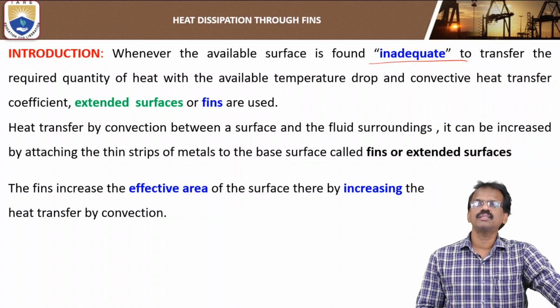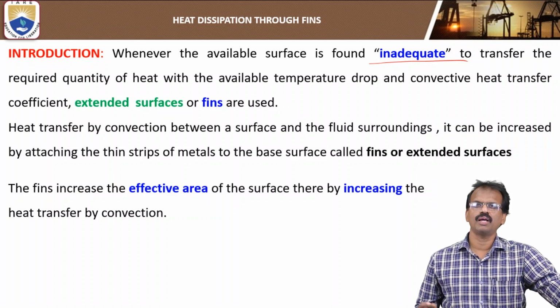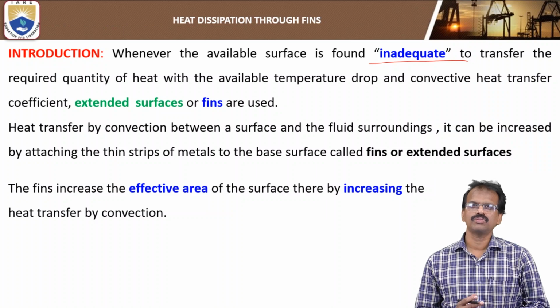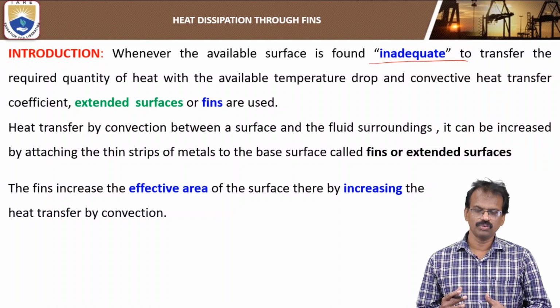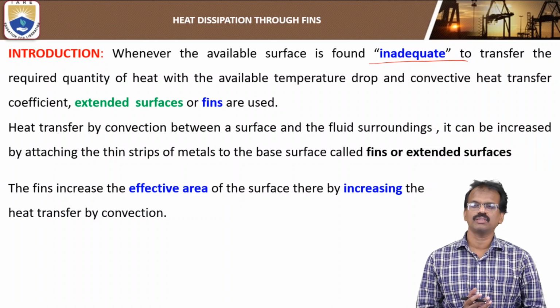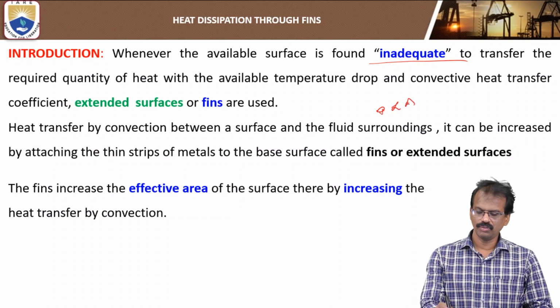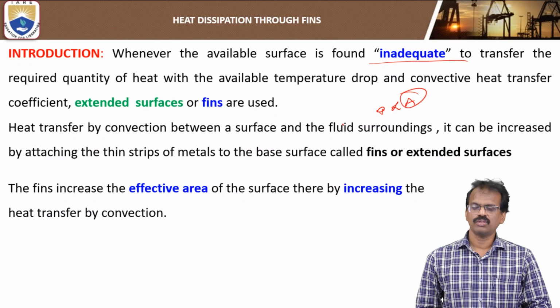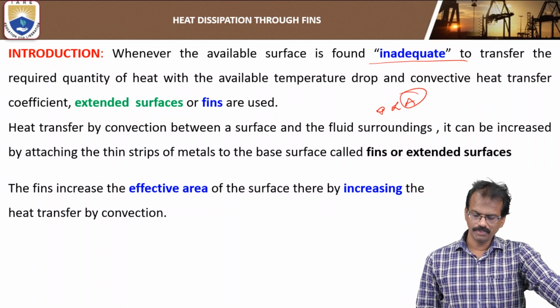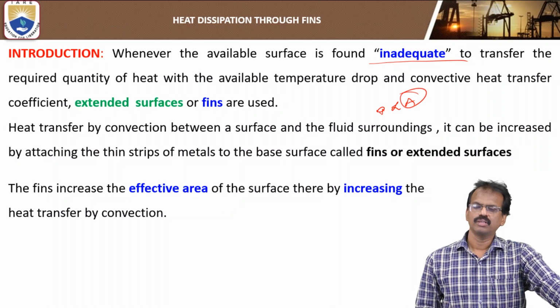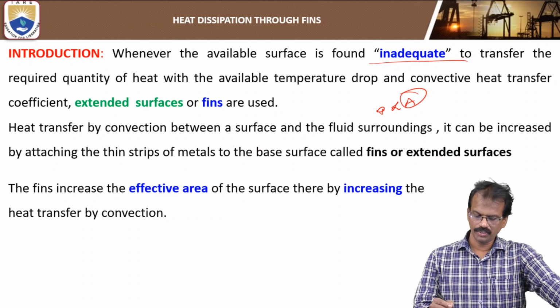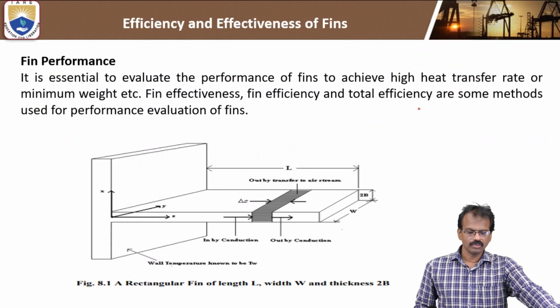To enhance the heat transfer rate, we add external fins to increase the effective area. Because Q is directly proportional to area, if the area increases, the rate of heat transfer automatically increases.